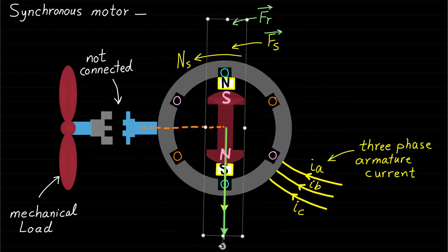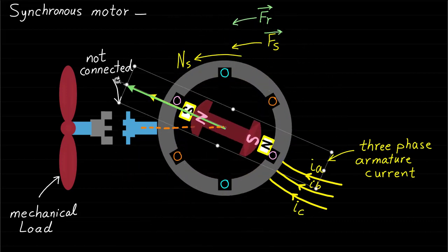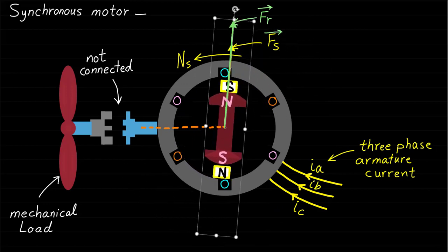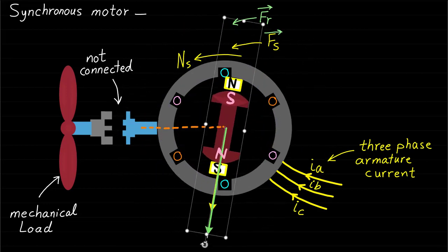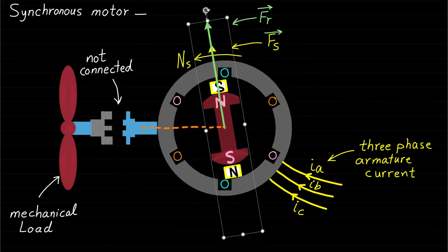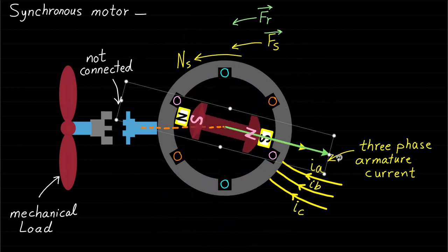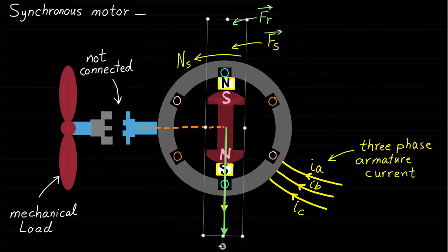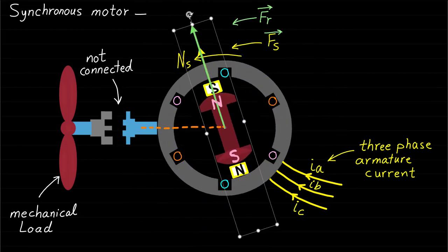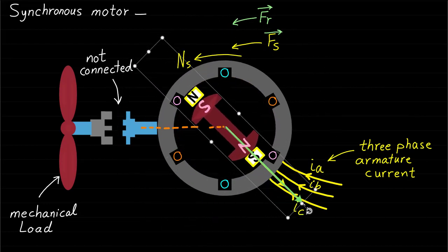It should be noted here that the synchronous motor is not a self-starting machine, but at this point we just assume that the rotor started by some method and followed the stator imaginary rotating magnetic poles.